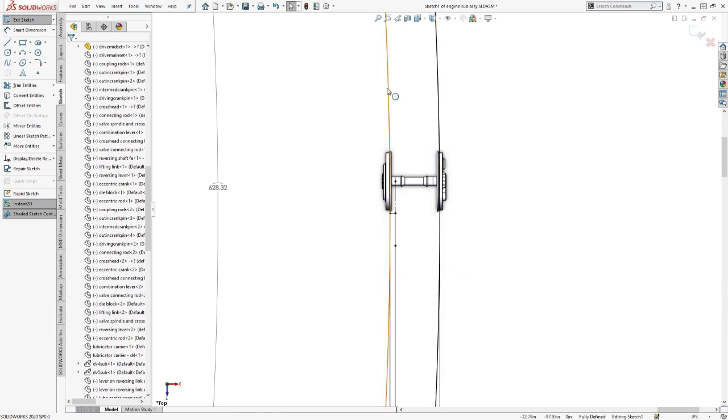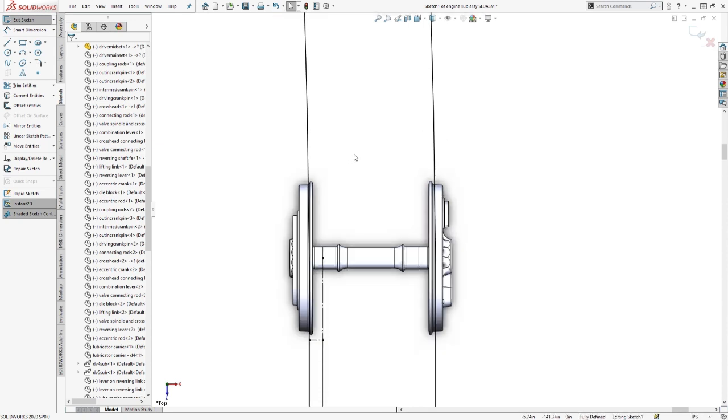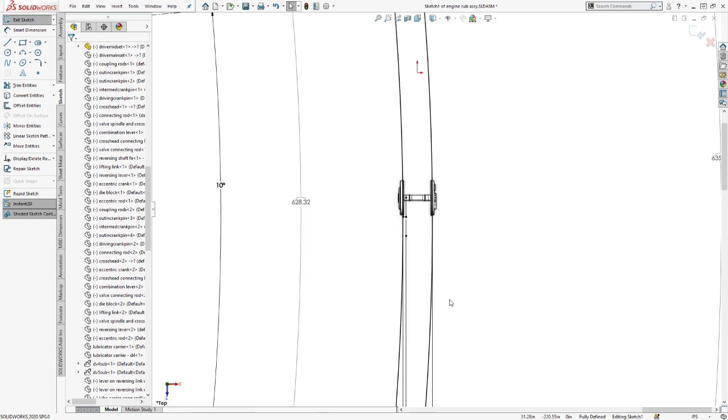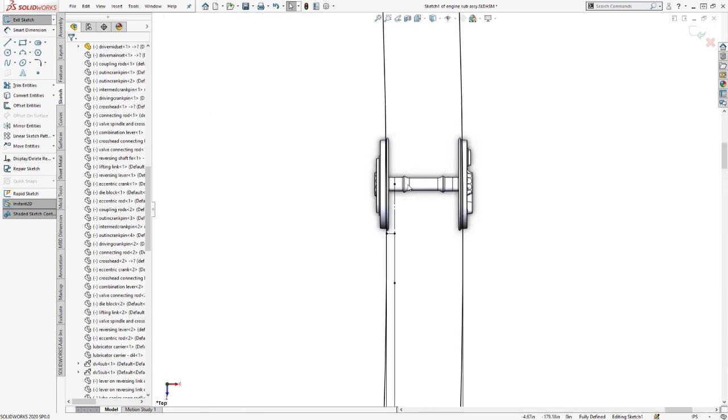The next one up, however, is going straight out, and this is curving away, so it can't hit the exact same diameter. And it doesn't have to. What it has to have is the same ratio. And so each wheel can find its own diameters. It's the ratio of arc length that we have to hit. So each wheel can be distinct.